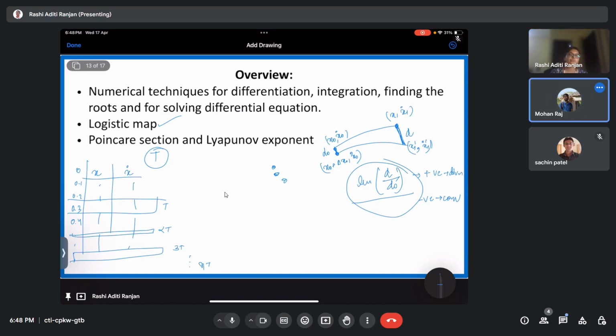How to differentiate that? There is this windowing we do with this kind of signal. However, I don't remember exactly about it. I would suggest you read much about it, but I'll just tell you briefly. We use a windowing function. If for a data we have noise, we define a window. For that window, we take the function and then we analyze it, and after that, we try to remove the noise from it. However, while you are taking experimental data, it is better that you use some kind of filter. Are you not using any kind of filter to remove the noise?